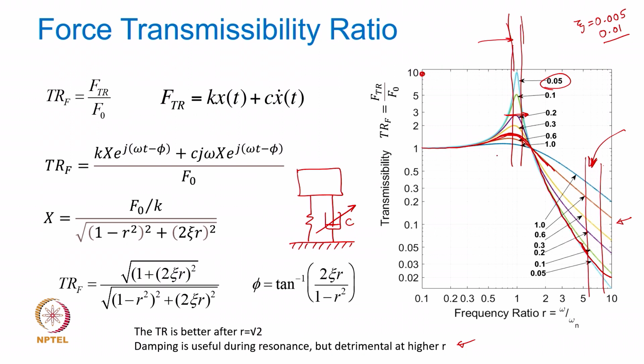So, the C value gets increased here by activating magnetorheological action, or the fluid which is there in the dashpot can be activated through some external activation energy to cause the damping coefficient to rise significantly, so that only in this period you activate it and generate a large damping, and the moment you go past this particular point, you deactivate it, so that the least damping works. Okay.